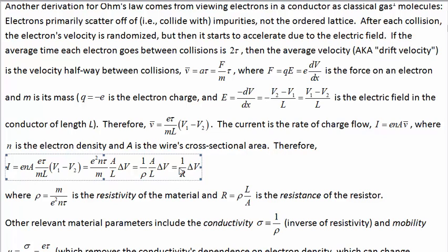So basically this tells you that the resistance of a resistor depends on some material property called the resistivity, and the length of the resistor: the longer that is, the more resistance it has, divided by the area. If it's got a bigger cross-sectional area, then we'd have lower resistance. That kind of matches your model for resistance.